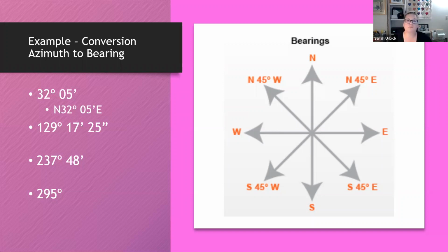All right. So we figured out what quadrant we're in. Now we know we're subtracting from our 180. When we do that, we get 50 degrees, 42 minutes, and 35 seconds, exactly what Olga posted. Thank you. As you've noticed, we're going around the circle clockwise. Our next azimuth is 237 degrees, 48 minutes. Where do you want to start? Walk me through. What would we do first?